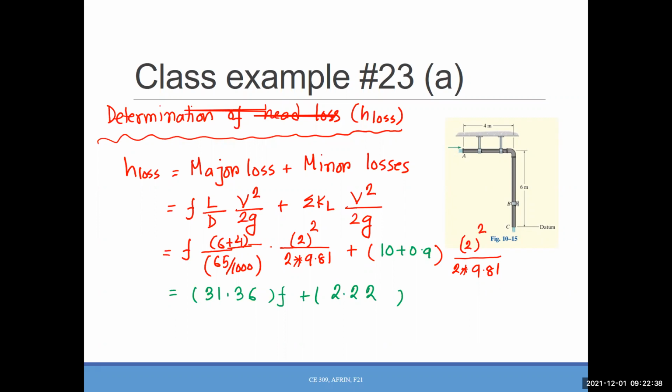Now, for any type, for calculating the friction factor, at first we need to calculate the flow type, whether it's laminar or turbulent. Because for laminar, it's easy. It's 64 over Reynolds number. For turbulent, we need to do something else. So that is the step here. Find the Reynolds number and determine the type of the flow. So that's what we will do now, okay?